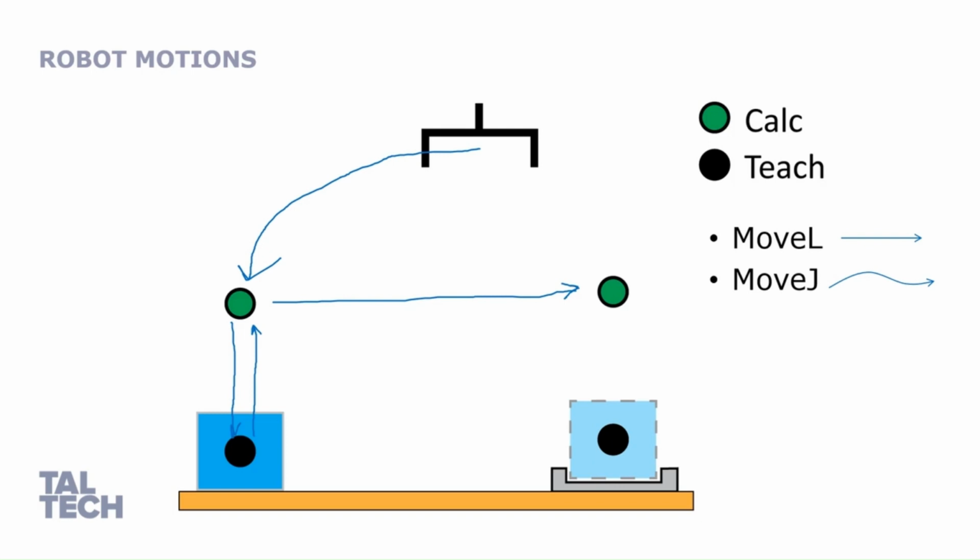When we have it, then we should move down to the placing part here, release the gripper, and then move up to the upper position. Why up? So that we can actually access the box after the robot has stopped working by itself.